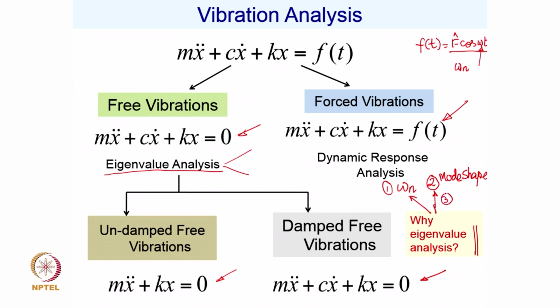The third thing that typically is mostly not discussed or considered, but is equally important for some mechanical systems of course, is understanding of stability of the system. So, the third objective or outcome of eigenvalue analysis is to understand stability of the system. Typically for rotor bearing systems, the analysis for its stability is important, and eigenvalue analysis does generate information as to whether the system is stable at different operating conditions, and therefore, stability analysis is also an important outcome of the eigenvalue analysis.